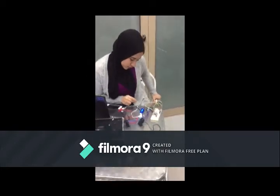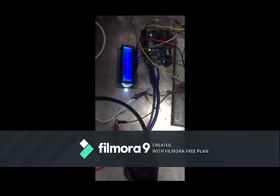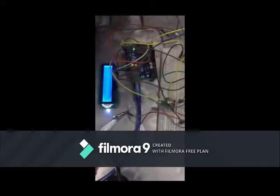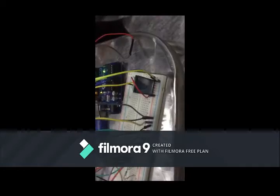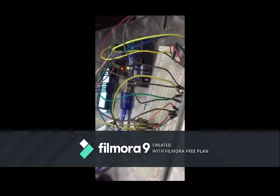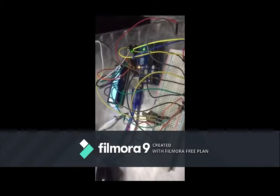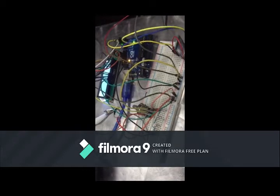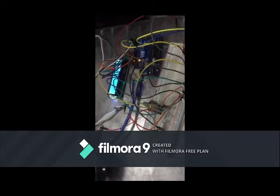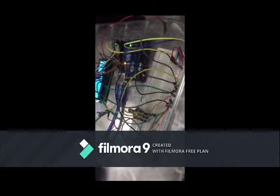We connected pins D3 to D7 to pins 2 to 5 on the Arduino board, and we connected the cathode of the LCD to the ground of our project, and the anode to the 5 volt of the Arduino. We also connected the enable and the VSS of the LCD to the common ground of our project,